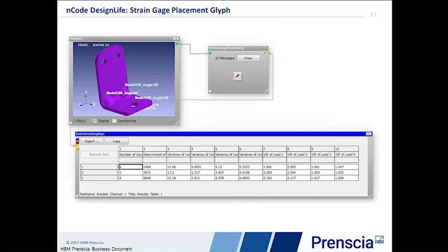If I have large numbers in these values, what they represent is that two or more load cases are some sort of scalar combination of each other. And if they were exactly a scalar combination, then it's impossible to solve, because when I'm solving my matrix, I'll end up dividing by 0. So these are useful for understanding whether I have applied loads that are purely unique to my structure, or maybe I've applied a load that is just representing another load that's coming in at the same time.